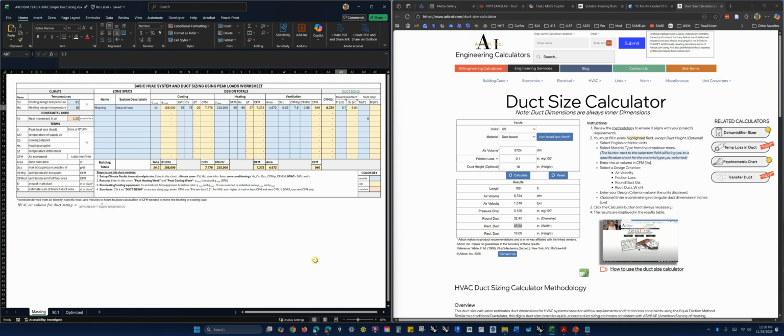Because we're just branching it off, but you're going to actually need more duct. You're going to need more duct surface area because these branch ducts are smaller, and that means that their surface area to volume ratio is going to be larger. You're going to have more surface area, and that's where the friction happens. So we actually just have a larger aggregate of branch duct square footage than we do of trunk duct. That calculation is done automatically in the spreadsheet modeler I've got here.